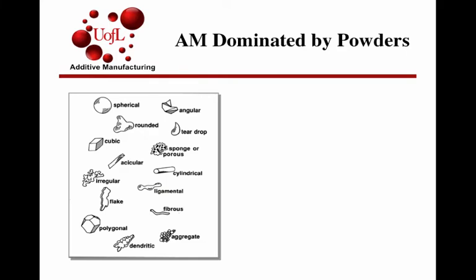In terms of additive manufacturing processes involving metals, you can use powders, wires, foils as possible starting materials or building blocks to add together to create a shape. While all these options exist, additive manufacturing of metals is dominated by the use of powders. The key focus of this class is to realize that there are a whole range of variations of powder attributes.